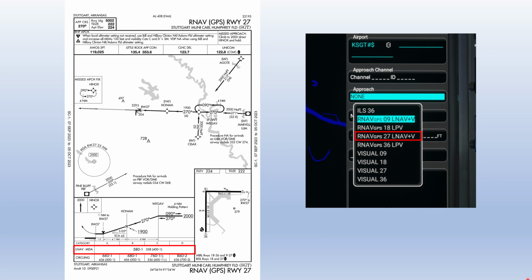We could treat that as a DDA at 50 feet and use it as a decision height if we wanted to do that, but it does not have any sort of vertical guidance minimums. We have to use the non-vertical guidance minimums that are on the chart, but we can load it up in the GPS and get a glide path.